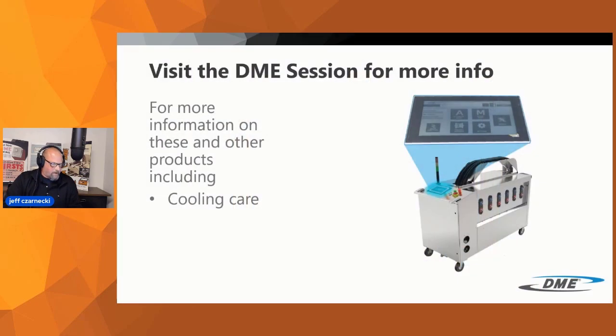Then after the event, in our sessions, we're going to be talking about our conformal cooling. As many people know, conformal cooling inserts can pose some issues and challenges with the water lines themselves getting clogged. And for that, we've introduced our new cooling care unit to help maintain and provide optimal cooling throughout the molding cycle.